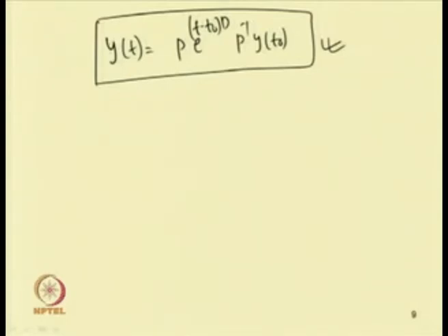If this perturbation grows, then the system will be unstable, according to our Lyapunov principle. If it remains within a bounded region, then the solution will be stable. Let this be the equilibrium solution. If we perturb it and it remains within this circle or bounded region, then the system becomes stable. If we take a point and it grows with time, then it becomes unstable.